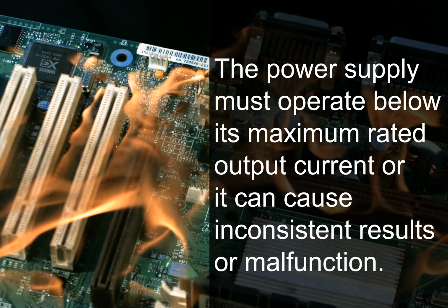How much current does my power supply need? A good rule of thumb is to combine the amount of drive current needed to meet the needs of the load and the current needed to power the controllers, and then add 10% as a buffer.